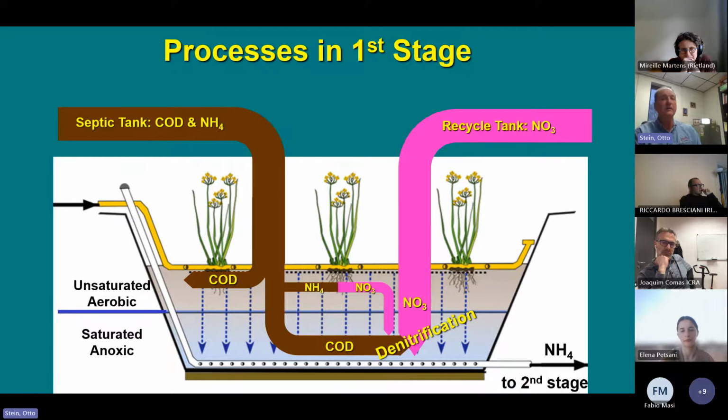So our COD to N ratio may not be as good as we thought it was, because we actually were loading more nitrate into that lower zone. So if we look at this again in the aerobic zone, then presumably that would increase COD removal and increase nitrification. Assume that has no effect on the nitrate, so the anoxic zone there can only receive what comes through. So we get more nitrate, less COD, and poorer nitrification if I had small doses of water coming in. So it's a double whammy, if you will: more nitrate and less COD.